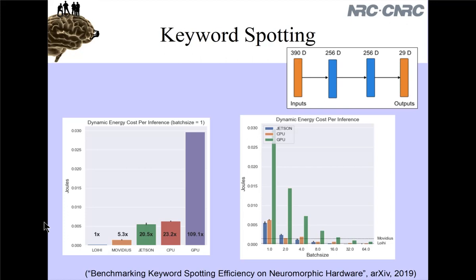One interesting, surprising thing here is just how much less energy efficient the GPU is than the CPU. That's a function of GPUs turning out to not really be perfect for running single neural networks. If you want to run a GPU efficiently with a neural network, you want to do what's on the right there, and that's this batch size parameter across the bottom.